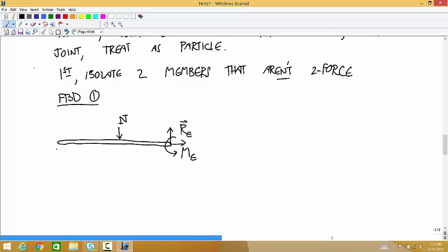But now we have to treat A differently, because A is connected to actually two different two-force bodies. Okay, so over here now, we have the force on member 1 by the pin A. Okay, we're not lumping the pin in with member 1 anymore. So the force that's applied to member 1 at this joint is the force applied by the pin. Okay, that's not an internal force anymore. Okay, ask me questions about that. Or express rage or something. Show some emotion.